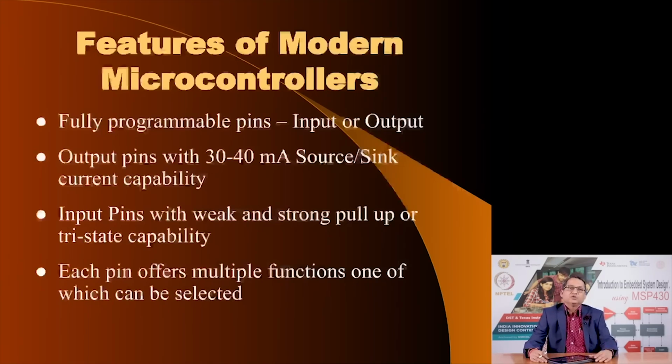Now, if this 20-pin device that I am talking of here is a microcontroller, you are left with 18 pins, and you could decide, let us do an equitable partition. Let us say 9 of the pins are digital inputs and 9 of the pins are digital outputs. So, obviously, any application which requires no more than 9 inputs and 9 outputs could possibly utilize this IC.